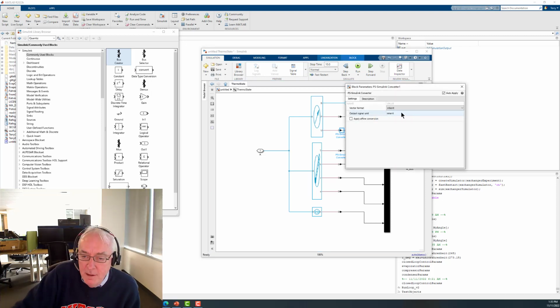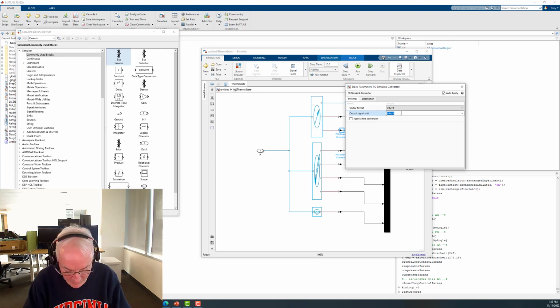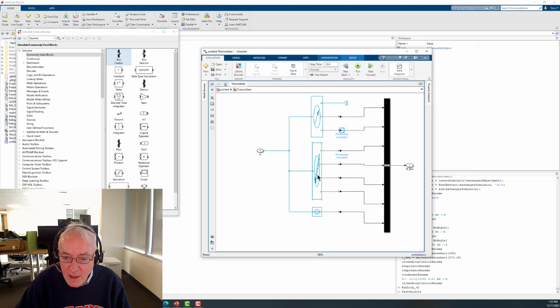Now, if you inherit, especially if you like metric units, meters and Kelvin and kilograms, going with inherit usually works quite well, but I'm going to be pretty specific here. I'm going to go kilojoules per kilogram, right? So it's a specific internal energy. And then I'm going to go to this H1, which will have the same units, and so I'm just going to drag that in, right?